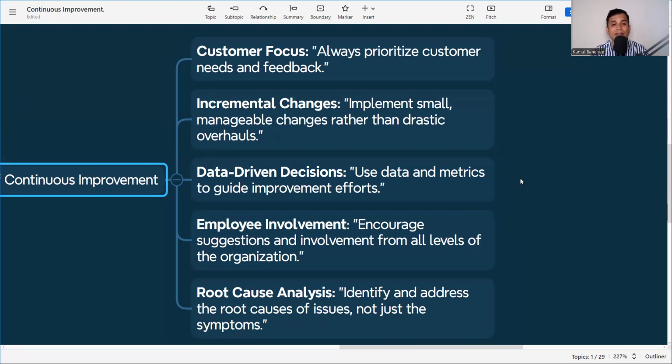Now, how can we collect the data? Let's take a small example. Suppose you are doing the concreting work and the cube strength is not coming as required. What is the difference in the strength, what is the variation, what is the temperature of the concrete at that time, what is the environmental temperature, how many people are working, how many reports, or how much training has been conducted? All the data is required in order to make a decision or an incremental change. Without data, it is impossible.